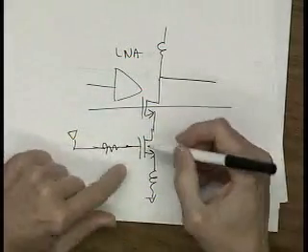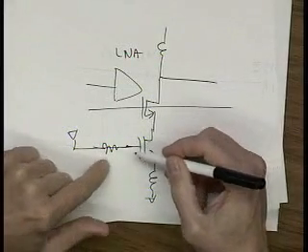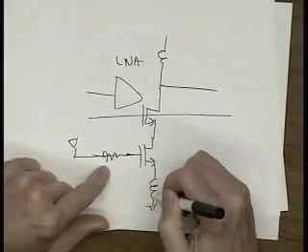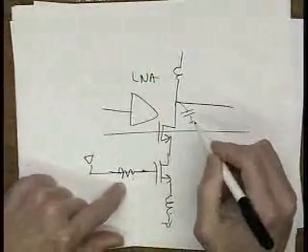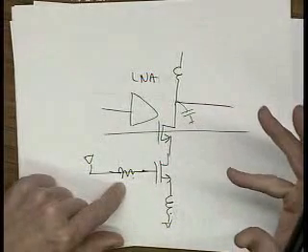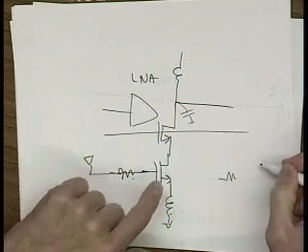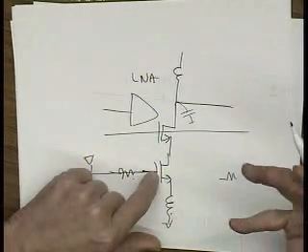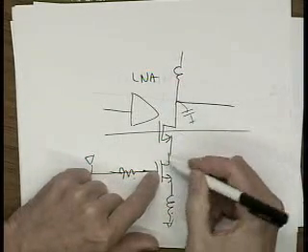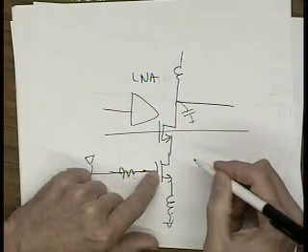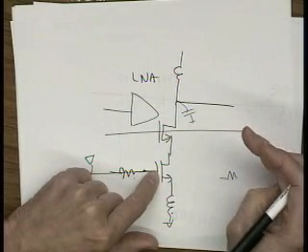Inductors do not have any noise. Capacitors effectively have no noise. They're all reactive elements. It's only resistors that have this 4kTR noise. And transistors. Transistors have an effective resistance. It's one way to think about it, right? What's kind of the effective resistance of a transistor? What would you think it would be? Any guesses on that?